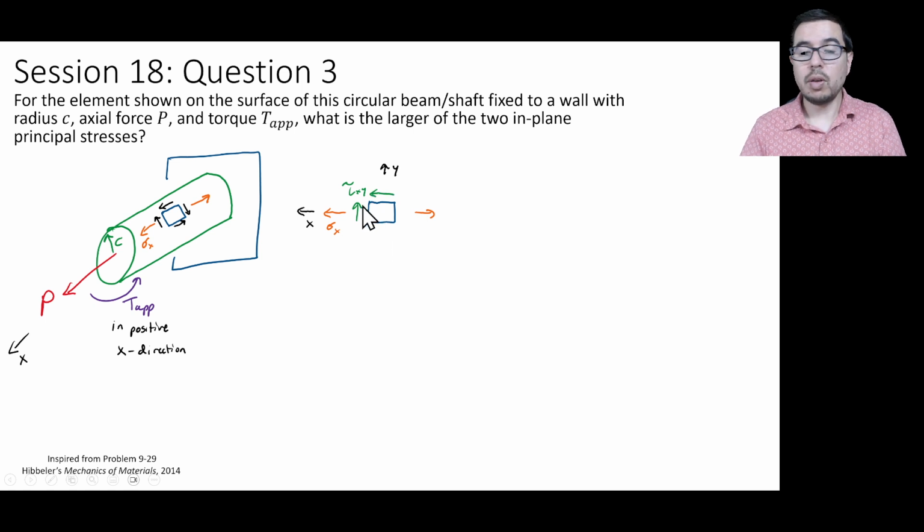We've also talked about this in the past: once you know one of the shear stresses on a 2D box or square, you can draw the rest. So it might be a good idea to say, okay, these stresses are going to meet in this corner, and then we have the other stresses, all with magnitude tau xy, that keep this element in equilibrium.